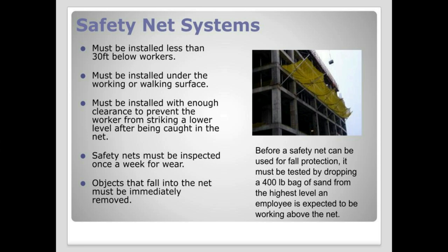Before a safety net can be used for fall protection, it must be tested by dropping a 400-pound bag of sand from the highest level an employee is expected to be working above the net. You want to make sure it's going to hold if a person falls into it.